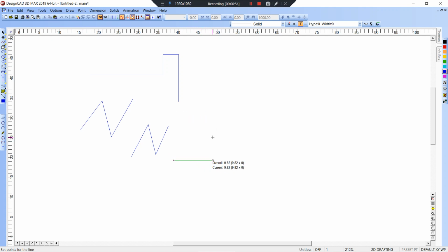So VH will lock it into ortho, and then hitting H again takes it out of the ortho command, and H again puts it back into ortho. It's kind of a nice thing. It's a real hotkey. You don't have to hit the hotkey and Enter, or apostrophe and Enter.